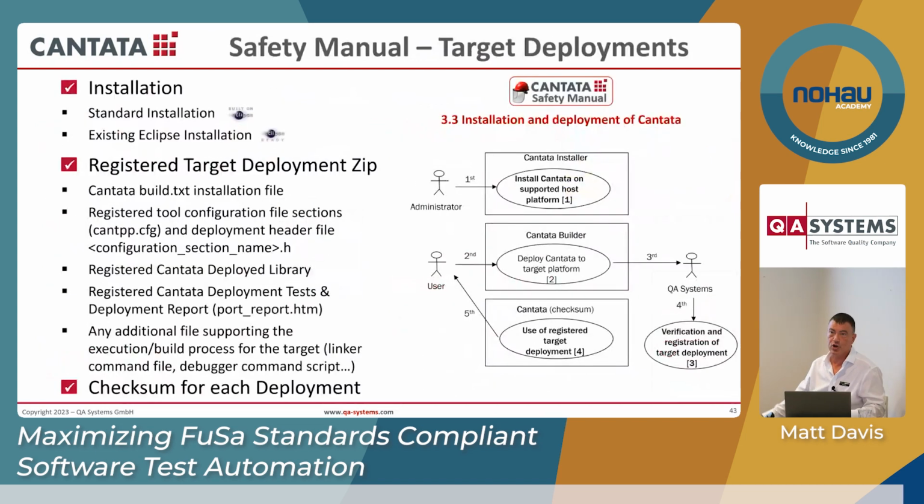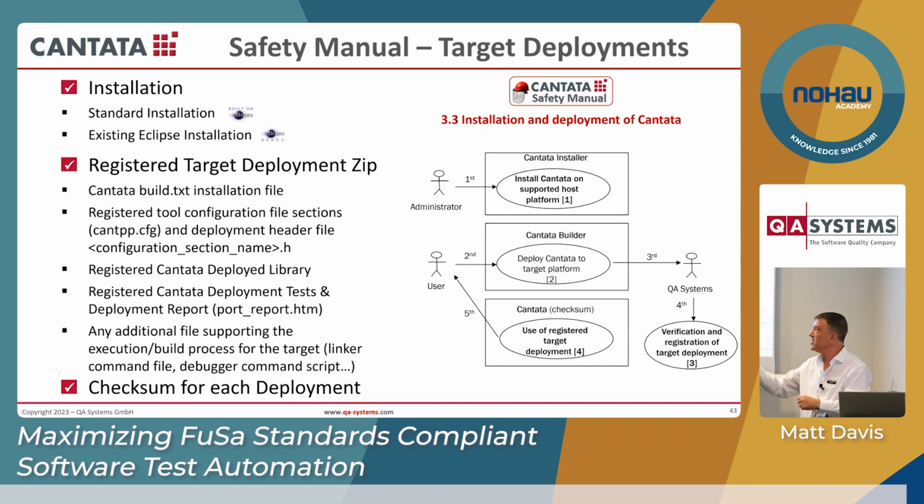And inside those documents, there is lots of information about use cases. So just to pick up on one, if you configure Cantata for your target architecture, you use the deployment editor, you create something called a deployment zip. You can pass that zip around and install it wherever you like. But if you don't register it with us and we tell you that it's checked and you haven't cheated, and we have had a few customers try that, basically here's the deployment, I didn't run any tests, can I use it? And we go, you can use it, but it's not certified.